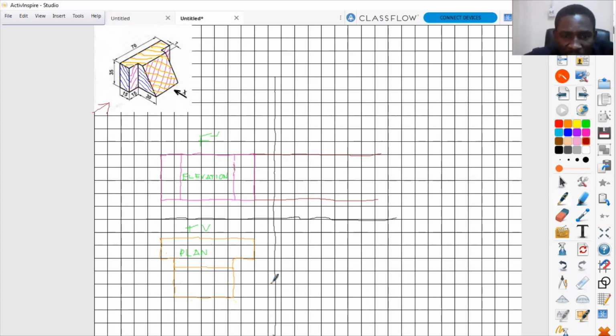Okay, but before we do that, the projection lines are essentially going to the right-hand side of the front view. My front view is here. Every projection line will be used at the right-hand side of the front view. Remember, in first angle projection, we are drawing the left end view, but it's going to be positioned at the right-hand side of the elevation or the front view. So whatever projection lines we draw from the top view are supposed to be taken up to where the end elevation, the left end elevation, will be located.